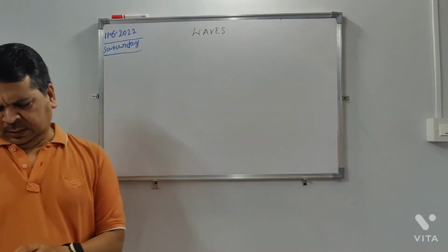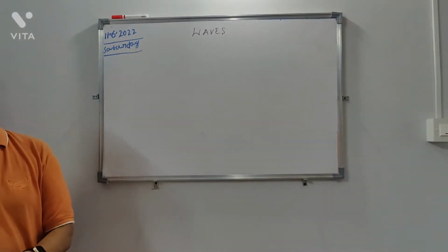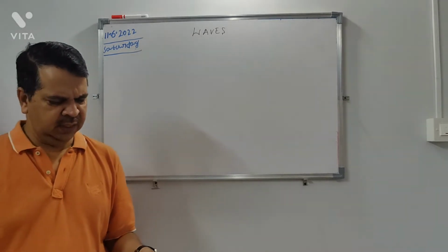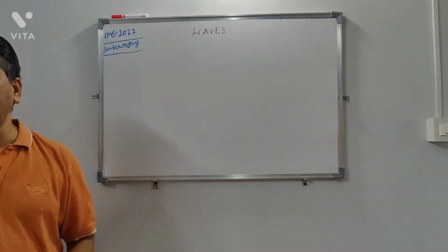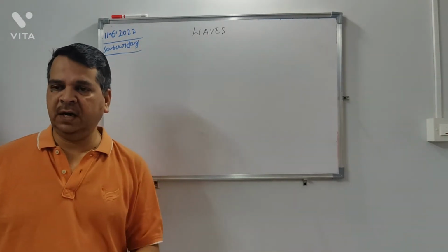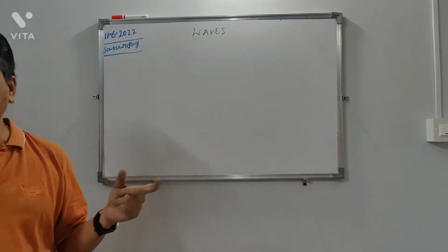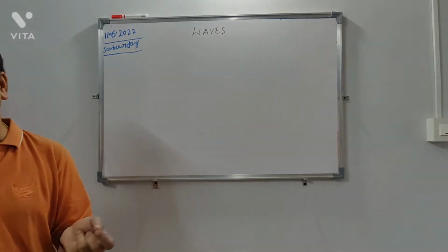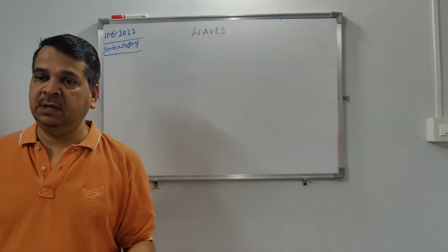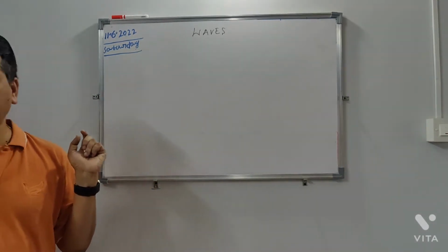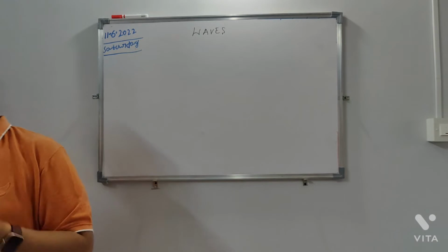Okay. And then there is zeroth law and third law and all that. And then specific heat and specific heat capacity. Specific heat is the amount of heat required to raise the temperature of unit mass by unit temperature. There can be two specific heats, at constant pressure and constant volume. So del Q by M del T is your specific heat. And only del Q by del T is your specific heat capacity. Okay.